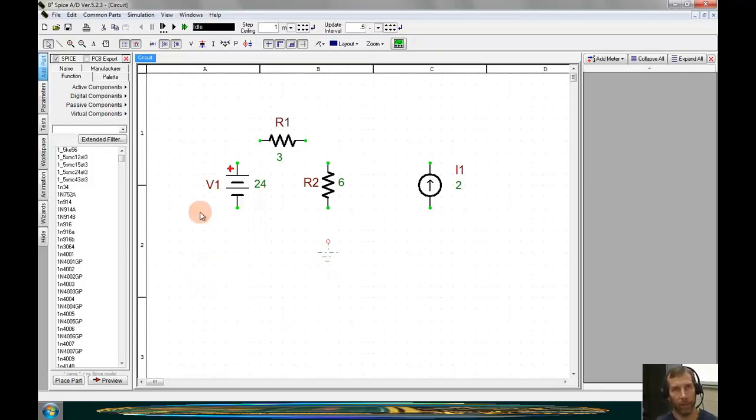Now, wiring can be accomplished by clicking on the toolbar item for wiring or by pressing the letter W on the keyboard. Once the wiring tool is selected, simply click on the green part's connector and draw a line to the desired part, double-clicking where we want that line to end. Begin a new wire by clicking on the next component to be connected and double-click on the endpoint. Continue this process until all the parts are connected as desired. Exiting wiring mode can be accomplished by clicking on the arrow key in the toolbar.